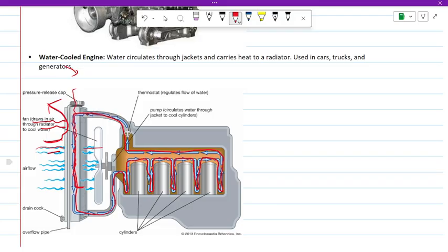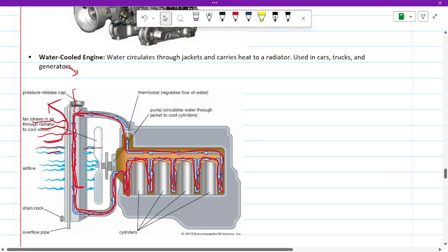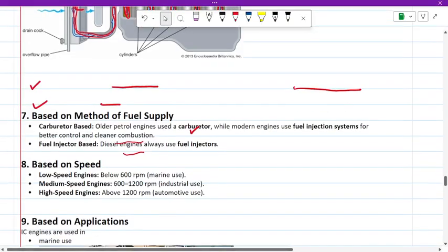Now it has a higher temperature, and this heat will be taken away by the air. Then once again the water gets cooled and goes into the water jacket again and again, takes the heat from the cylinder and gives the heat to the air, and the air is taken out by this fan.